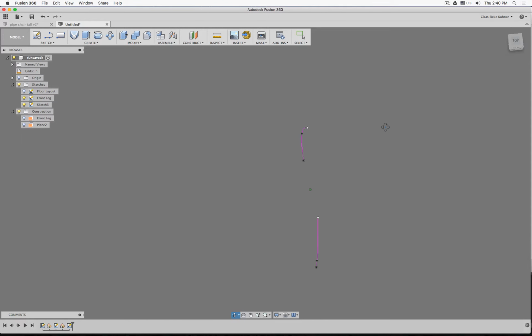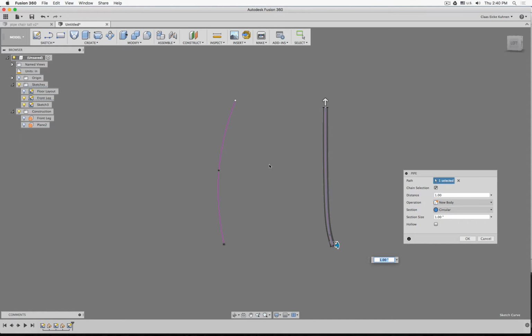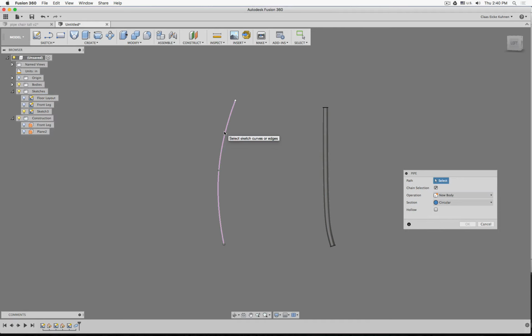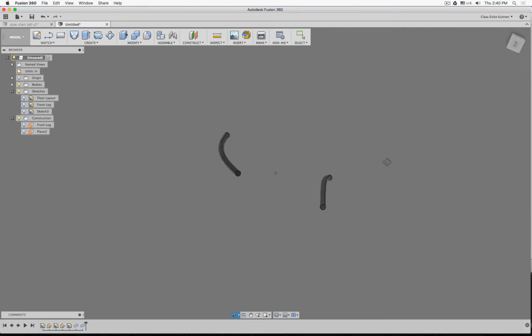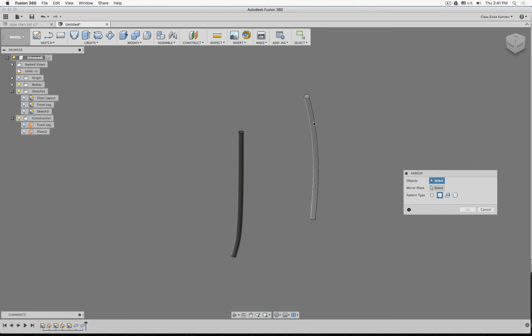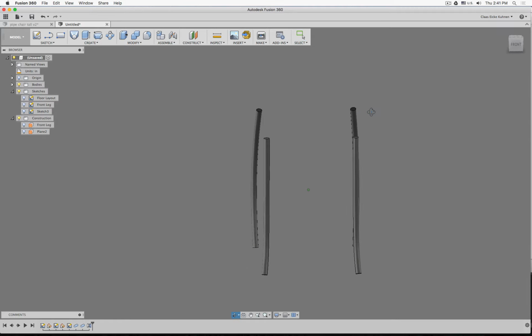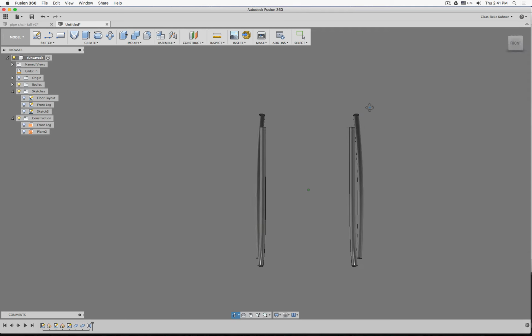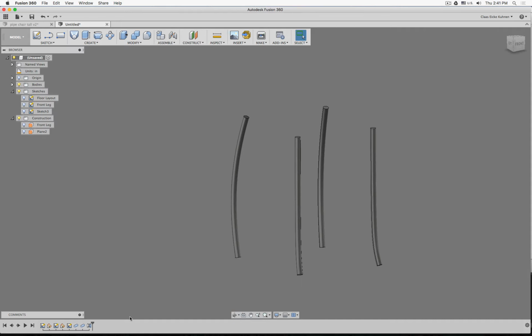Let's click stop, and now we see, if we take a look from the top, we have these two splines. And when we go and create a pipe, maybe with an inch, right click, repeat pipe, click OK, and there we have these objects. Nice. We can maybe for the moment turn on the mirror command, select these two, mirrored along this one, so I can see maybe how this looks. Not too bad. Okay, good.